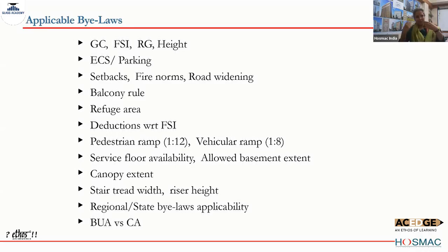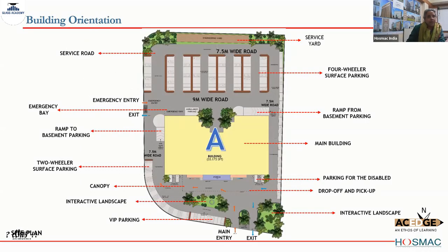Let's go to the next one. This is really extensive. So here is the site. You will see that the longest side of the building, which is the yellow building, is towards north. So we have tried to put inpatient rooms on that side to harness diffused light, not very harsh sunlight, but pleasant sunlight. This site was in Rajasthan, very hot. So the north side, luckily, we had the fortunate coincidence, I would say, where we could utilize the north light on a larger surface.